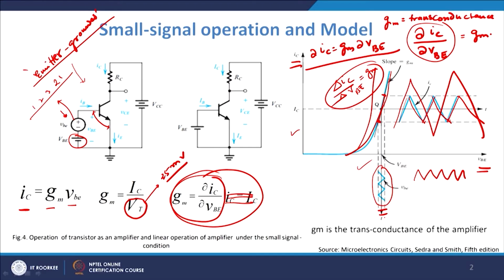So, that is the small signal model, and in the small signal model we will learn one important characteristic, transconductance gm. gm is defined as the transconductance, which in this case happens to be del IC del VBE, right, and it gives me an idea about sensitivity. So, if I know the base to emitter voltage, I can predict the value of the collector current directly by multiplying gm with the change in VBE, and that is quite an interesting phenomenon.